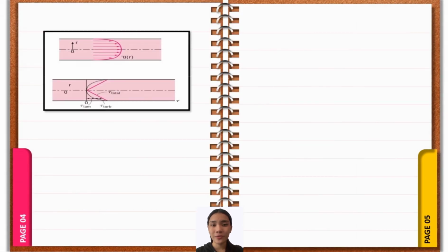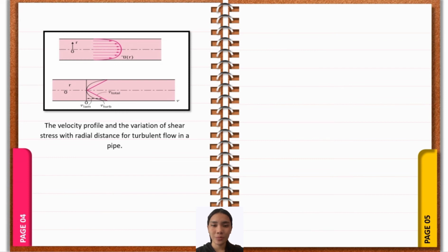Even when the average flow is steady, the eddy motion in turbulent flow causes significant fluctuation in the values of velocity, temperature, pressure, and even density. The first figure shows the variation of the instantaneous velocity component u with time at a specified location, as can be measured with a hot wire anemometer probe or other sensitive device.